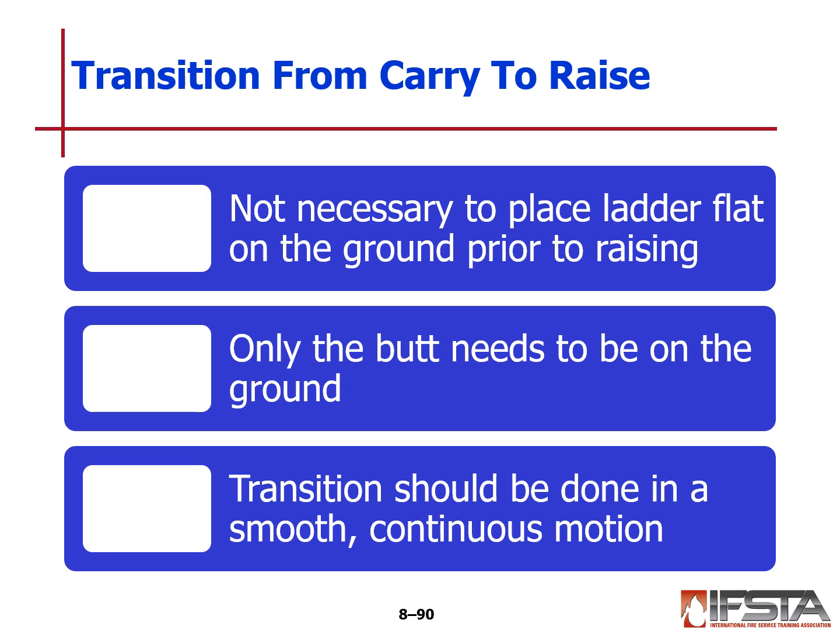When you do this transition, you want it to be smooth, a continuous motion. Please make sure that you look up and check for overhead obstructions, because you're literally walking, and as you walk, you're going to begin to transition into and do this raise without stopping. And so it is very easy to completely forget about looking up and seeing if there's overhead obstructions, especially at nighttime.